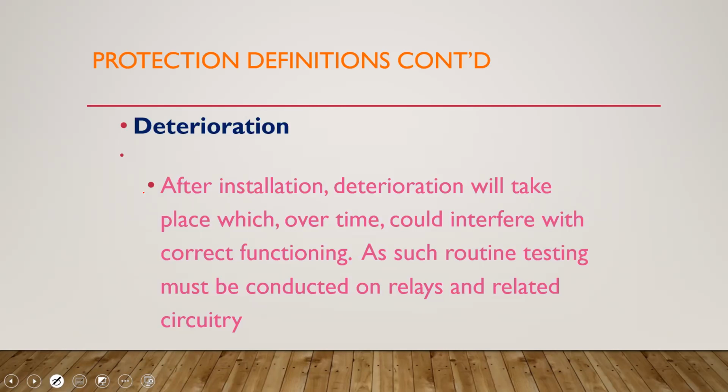You have your transformers that you have to carry out maintenance on. For many of these transformers, you have a little pipe at the side of the transformer that you take some of the oil from and test it. Based on the amount of sedimentation in the oil, you know that there may be a fault on the transformer. And these faults, as I said earlier, are some that may require not isolation, but an alarm.